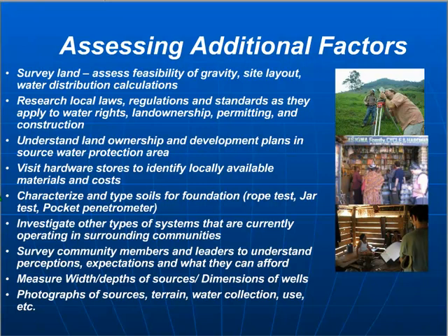It's important, too, to characterize the types of soil, especially for any foundations that you might be needing to design. I suppose this is more applicable for a tank storage design, but during that first assessment trip, even when you're at that point of selecting a source, it's important to understand the types of soils at the project site so that you can understand how to design the foundation of whatever structure.